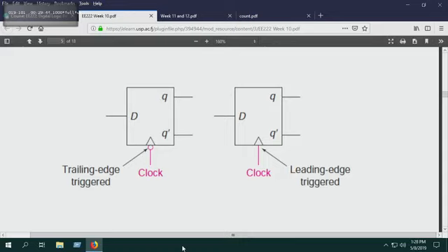So that's another problem. So again, we researched on the internet and found that you have to reset your computer board. How do you reset it? You either get the onboard diagnostic kit and do some kind of programming over there, or if you've got this particular model of Nissan, you press the brake pedal once, then lift it, then press it again twice, like a Morse code, 1010111001, and then press this button here, and did that, and then it worked, and that particular pinging noise disappeared.